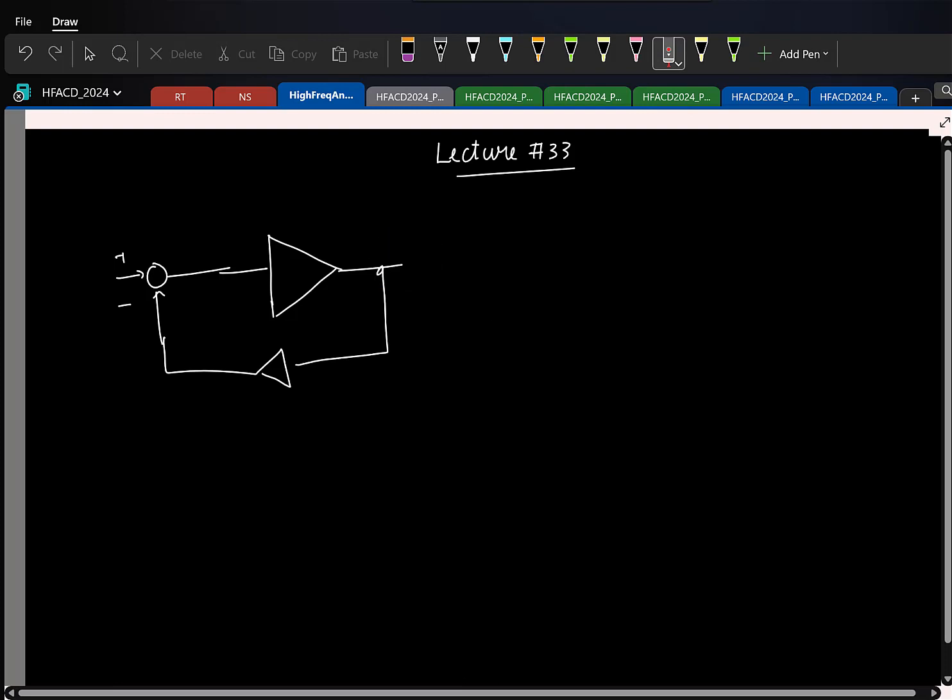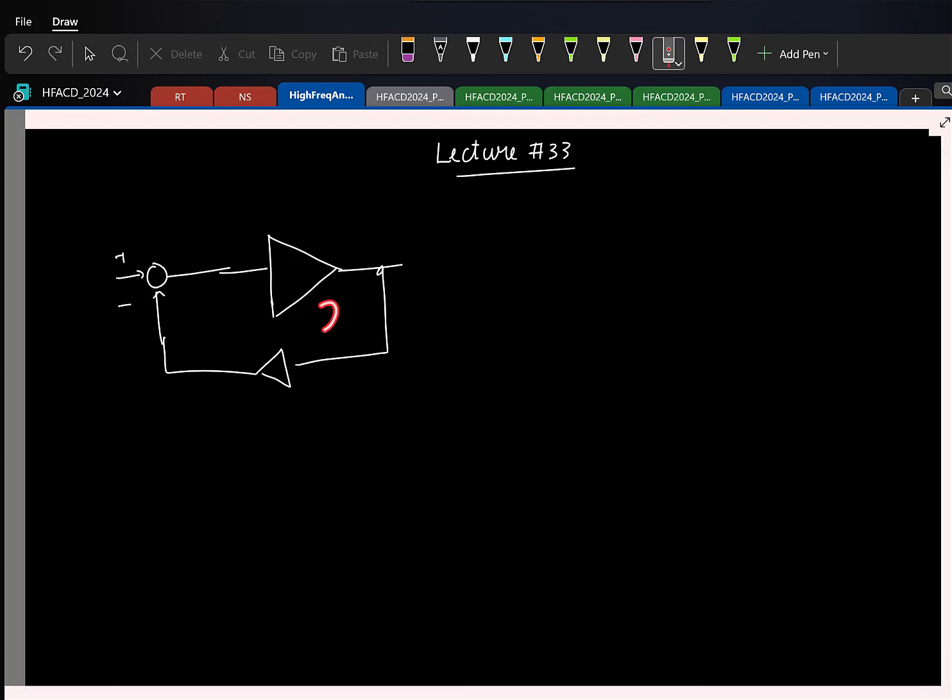And that essentially happened because as long as you have a large enough loop gain, the error signal here is going to be small. So although your actual input signal will be swinging so much, the actual signal that excites the nonlinear system is going to be very small. So it's going to behave more linearly, right?